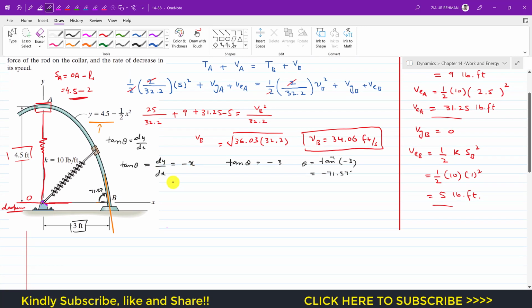normal and tangential coordinates, let's say that the collar reaches here, so now the collar is at B. This will be our tangential axis, and the normal axis is going to act towards the center of the curvature. Let's say that this is our normal. So if this is the horizontal x-axis with which this angle is made, 71.57 degrees, this normal is perpendicular to the tangential axis.